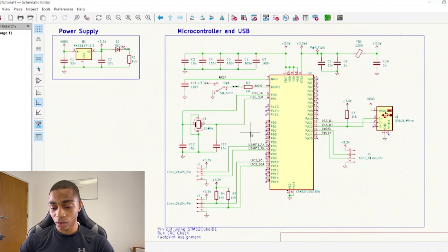Now, if we come over here to our pins 32 and 33, we have our USB, universal serial bus. And I think what's cool about our USB is not only is it a communication protocol, so we can communicate to our microcontroller through our USB, but we can also get power through our USB. So in our case, we'll be getting power from our USB. This is a USB micro, and that power is going to be VBus, and it'll be 5 volts coming in.